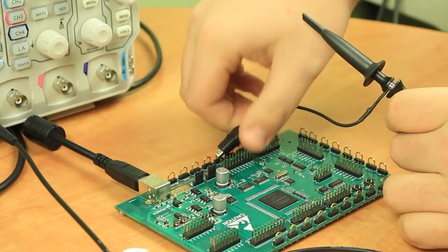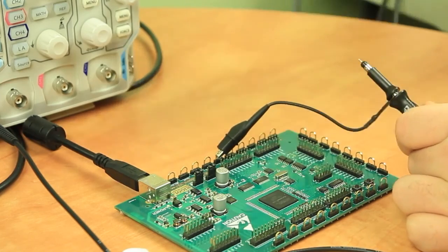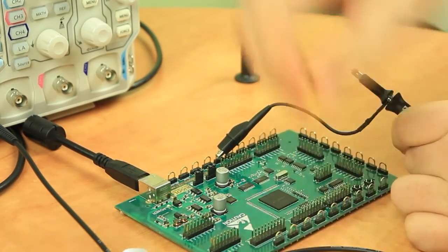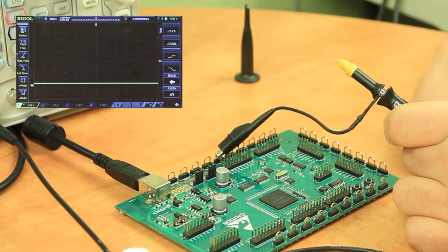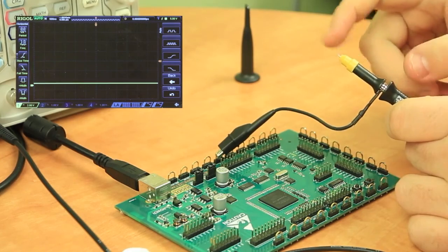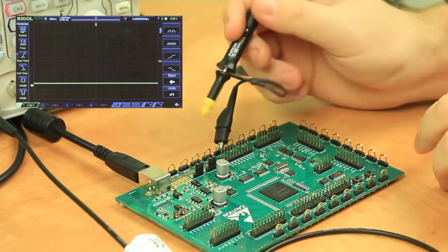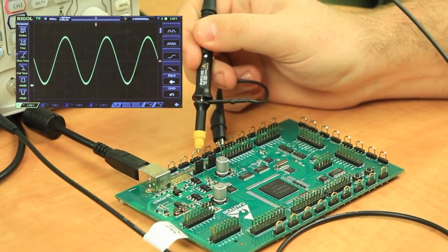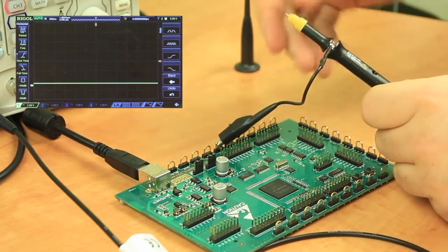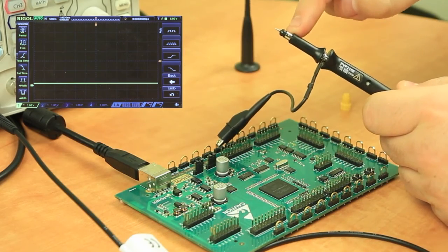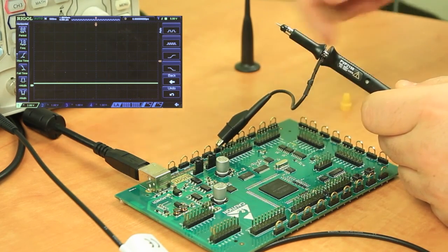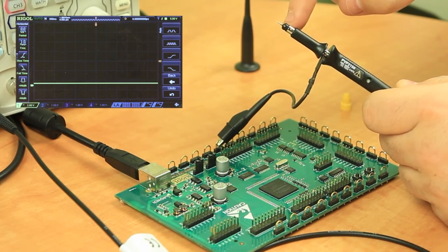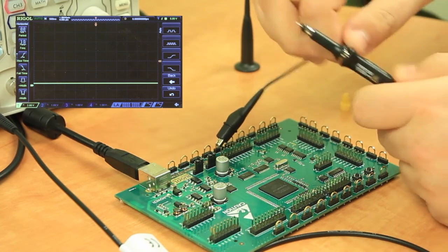Next, I'm going to disconnect the probe hook but leave the ground on. I'm going to take it off and push on the insulating cap. So this is covering the ground on the probe itself, and now this tip is where I'm capturing the signal. So I'm going to capture the same sine wave with just the cap itself. As a side note, this metal ring here and the metal ring here are both ground, so the insulating cap is just covering this so you don't short against this to the tip.